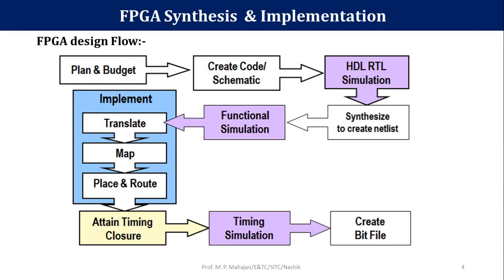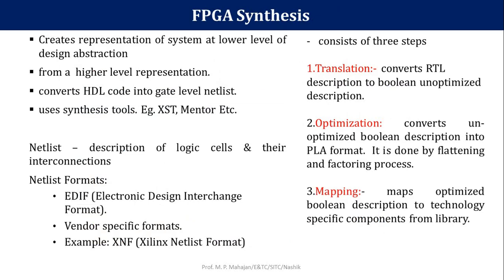Once implementation is completed, you have to attain the timing closure to check the performance of your system in terms of delay. Then perform the timing simulation to generate the timing reports to see whether your system will attain the performance as per the customer requirement. And finally, generate the bit file, and that bit file will be downloaded via the programming cables into your system hardware.